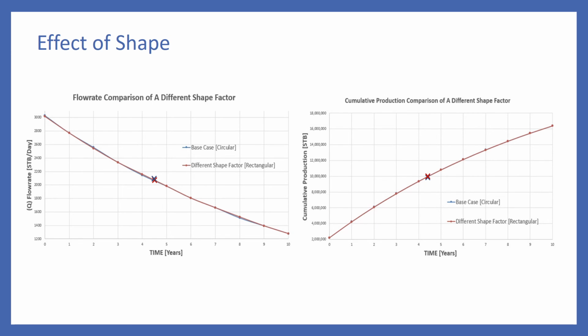Even for the 4x1 rectangle, the difference is only noticeable at very low pressures. The similarities in IPRs at high pressures prepared us for the results we received. There was a negligible amount of difference in the 2x1 production rate. After simulating the first 2 years of the 4x1 rectangle and receiving very similar results, we chose to neglect it and conclude that choosing different drainage shapes for the Dietz model most likely does not have a significant effect on production.